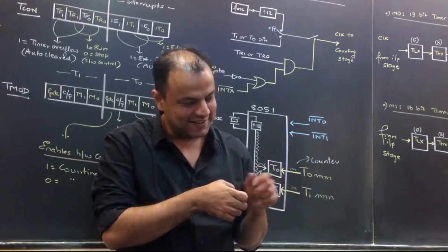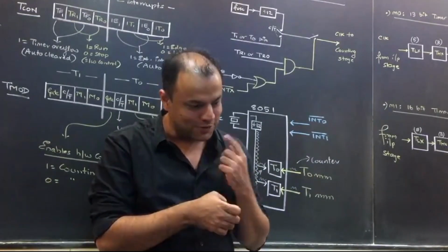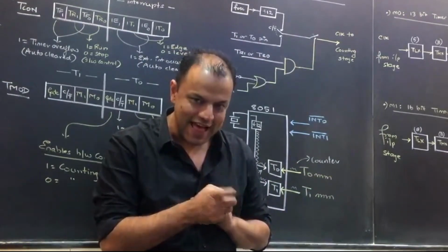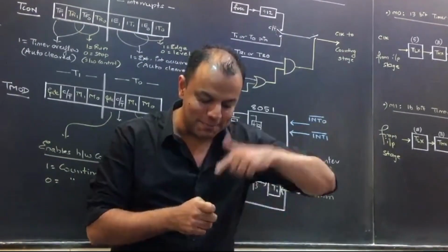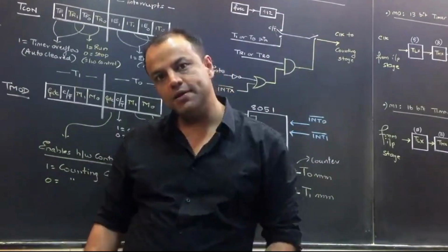On the other hand, think of a machine gun, an automatic rifle. You pull the trigger, a bullet is fired. Don't release your finger, let it still remain pulled. Bullets will go on getting fired. It is not interested in the pulling action. It is interested in the pulled position. It is level triggered. Tell me, did you understand this?